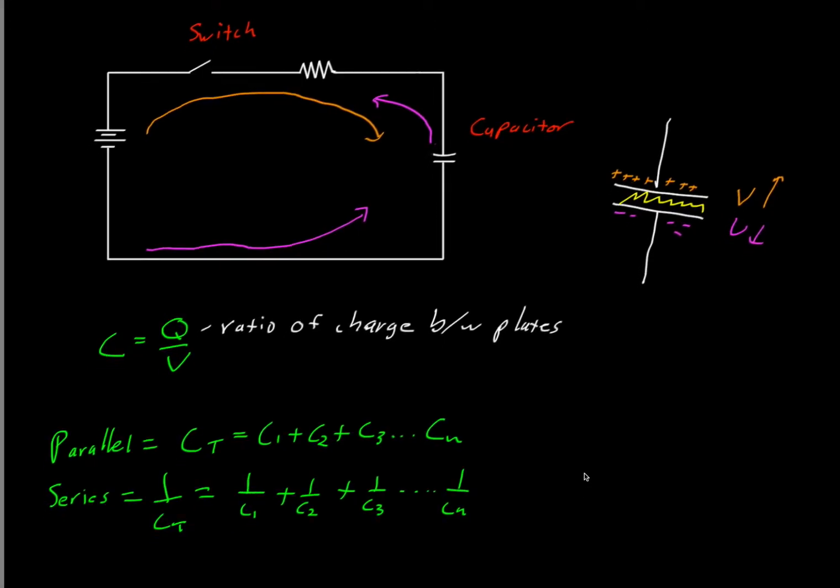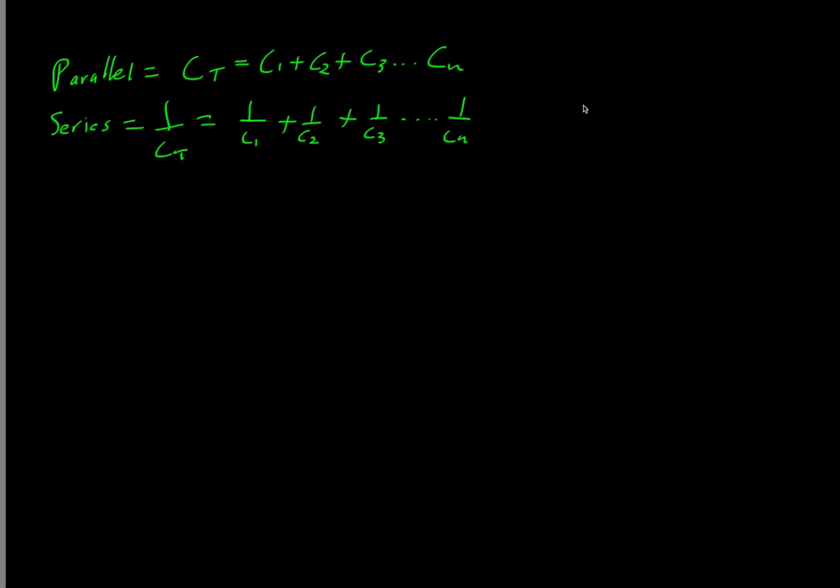So you can see, based on the fact that it has stored energy, there's a potential for work to be done. So what is the formula for work, and how does that actually occur? Well, work is done by the stored energy, by the stored charge. So we can take that, and based on the fact that it goes from 0 all the way to Q, which is the maximum stored charge, and it is directly related to voltage, we're going to integrate that curve with respect to the charge. Integrate voltage with respect to charge.